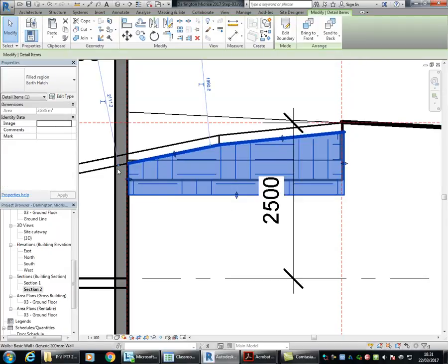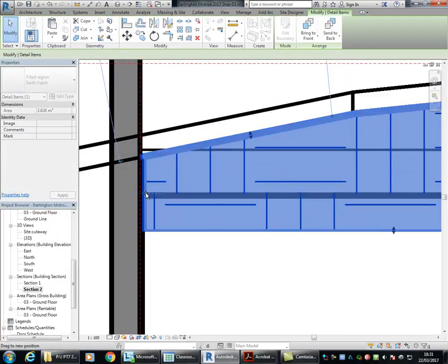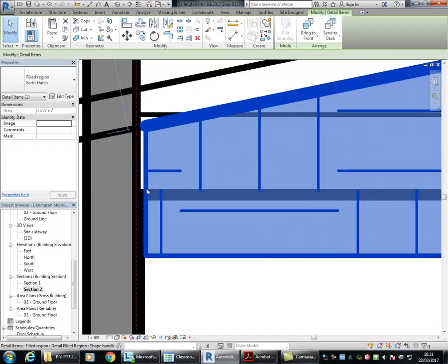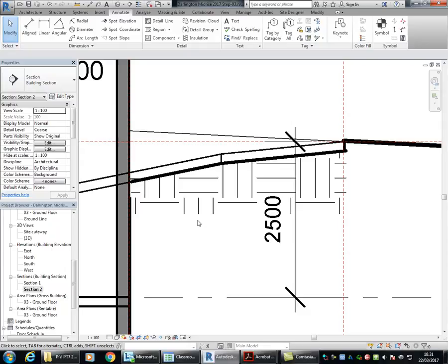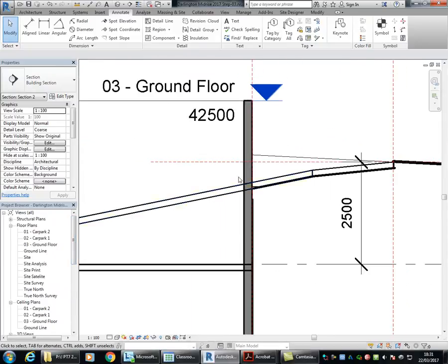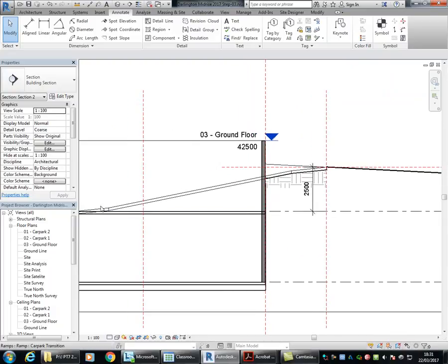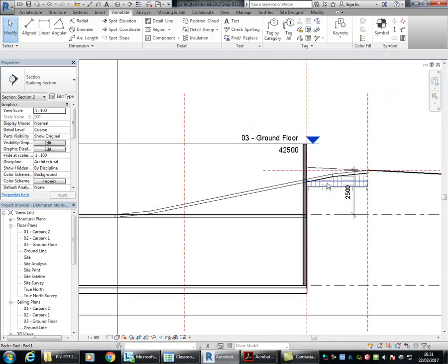So that should be more than enough to give you the setup for the ramps. And even if it's not the final ramp that you might know you will need, it's good just to put in a ramp that meets those controls, and those slopes especially, and use that as a working out tool to establish the heights, particularly the access way, also the length of the ramp.